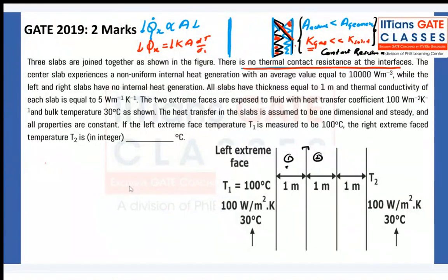Look, convection heat transfer will not work here. Why? I'll tell you why. Look, these voids are very small voids, right? So whenever air or any gas is trapped here, it will not move much, right?